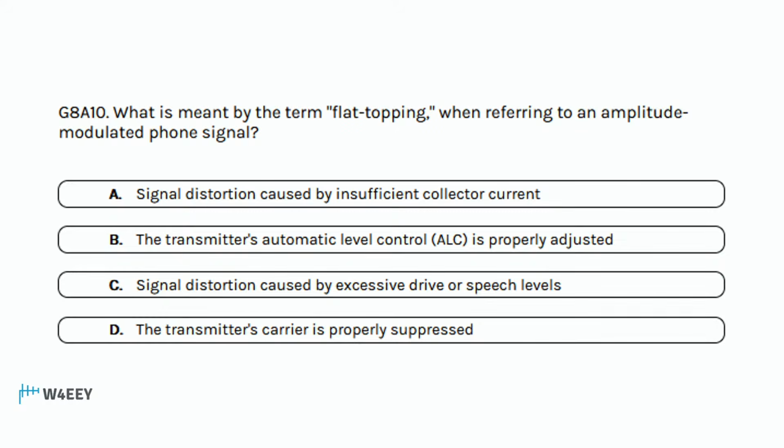And what is meant by the term flat topping when referring to an amplitude modulated phone signal? Charlie. Yes, Charlie. Signal distortion caused by excessive drive or speech levels, you clip off the top and bottom peaks.